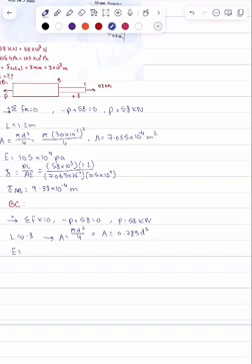E equal 105 times 10 power 9 Pa. Delta equals PL over AE, 58 times 10 power 3 times 0.8 over 0.785 D2 times 105 times 10 power 9.